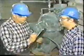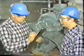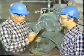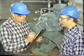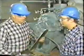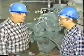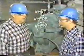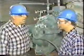Well, Gene asked the same types of questions. The operator told him there was too much runoff. The runoff came from around the gland follower. The excess leakage appeared only at the outboard packing, not at the inboard packing. The operator first noticed an increase in leakage 2 or 3 shifts ago.